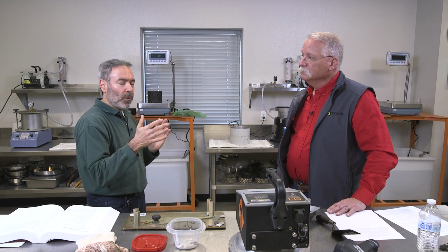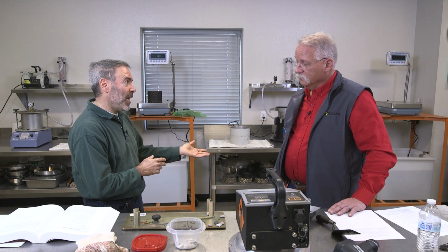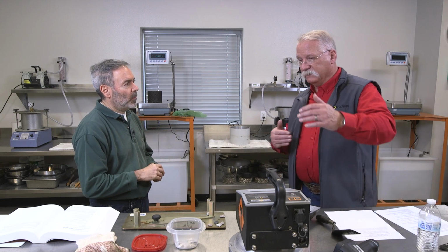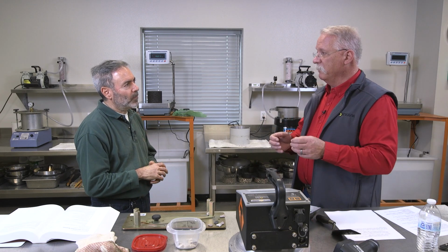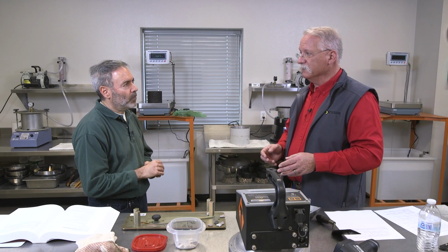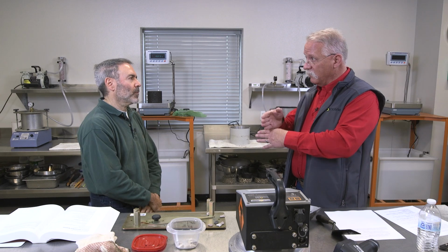And a random sample means random what? So if I'm taking a core, it's at a random location within that sublot. Length and width with offset. If you're taking a hot mix sample from the truck or at the plant, that has to be a random location during production. So anywhere in that sublot theoretically could be tested by the random number. And that keeps it from like, well, I'm always going to sample this load or this part of the mat out on the roadway because I know it's going to pass. That's not the point. I want to let the random sample fall where it may.